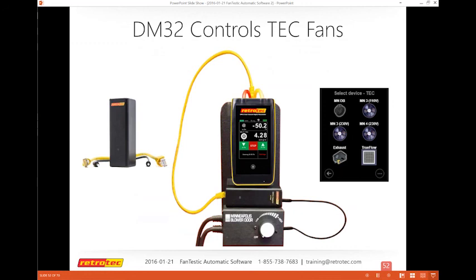You cannot use the Energy Conservatory gauge, but you can use the Retrotec gauge, and the DM32 will control the TEC blower door completely automatically, as though it was a regular Retrotec fan. So if you're looking for additional fans to do a large multifamily or large building test, you can get some additional Energy Conservatory fans and make your system work.